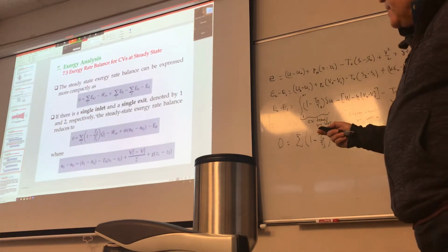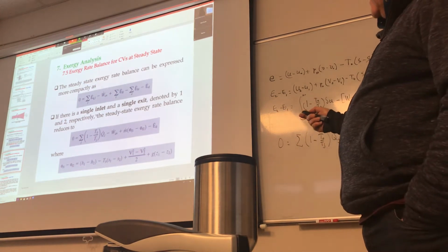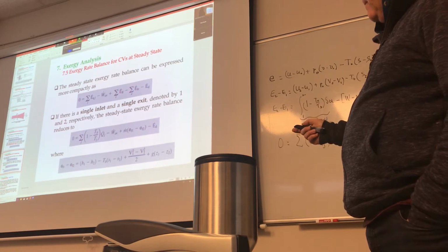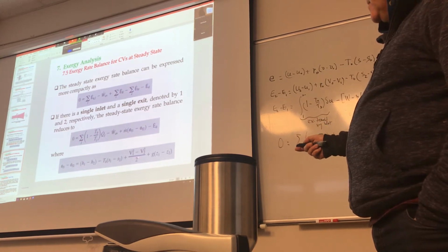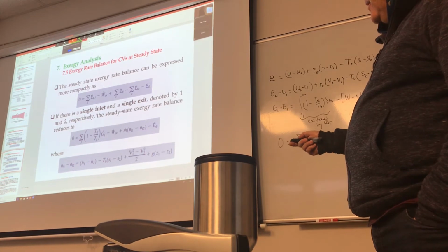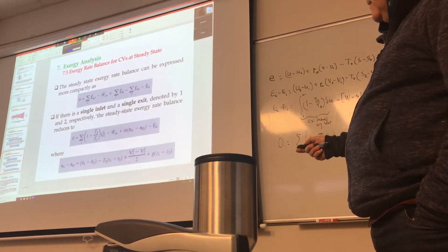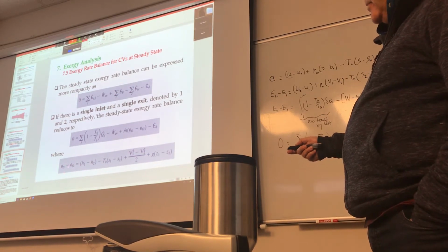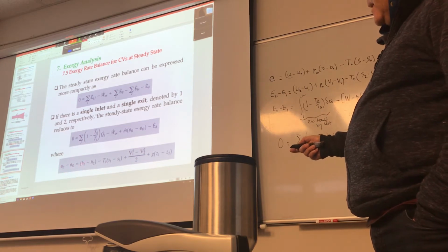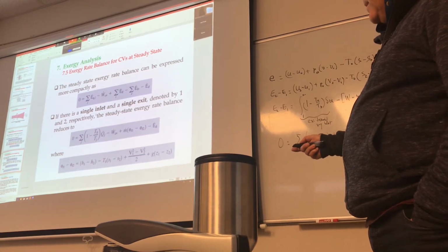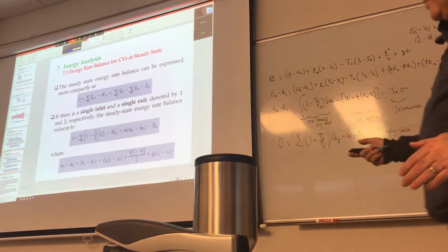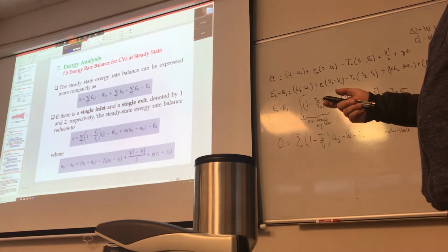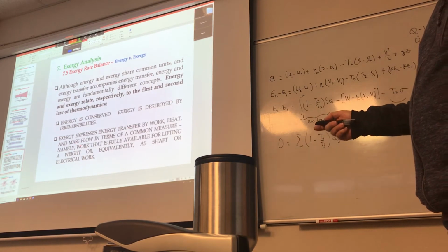Now, the steady state can be written more compactly in terms of symbols, but the one that is most used is essentially this one. EF1 minus EF2 is the exergy exchange between two states, as H1 minus H2, minus T0 times S1 minus S2, and the rest of it. So the whole story, when you talk about open systems, is to evaluate that term.